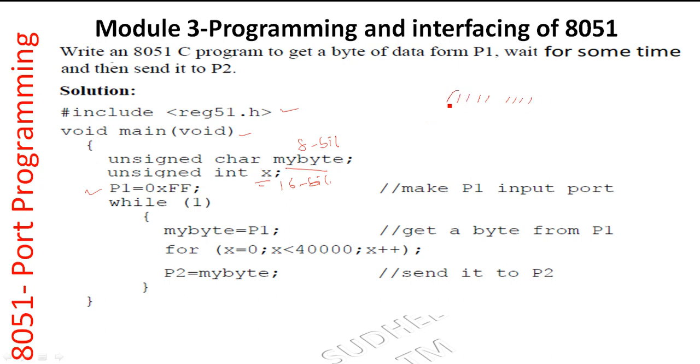So we are writing logic 1 to P1.7 down to P1.0. Every bit of port 1 is written with a 1 to make port 1 an input port. This is a compulsory part to configure the port as an input port, while configuring output is not compulsory; we can do without writing 00 to port 2.